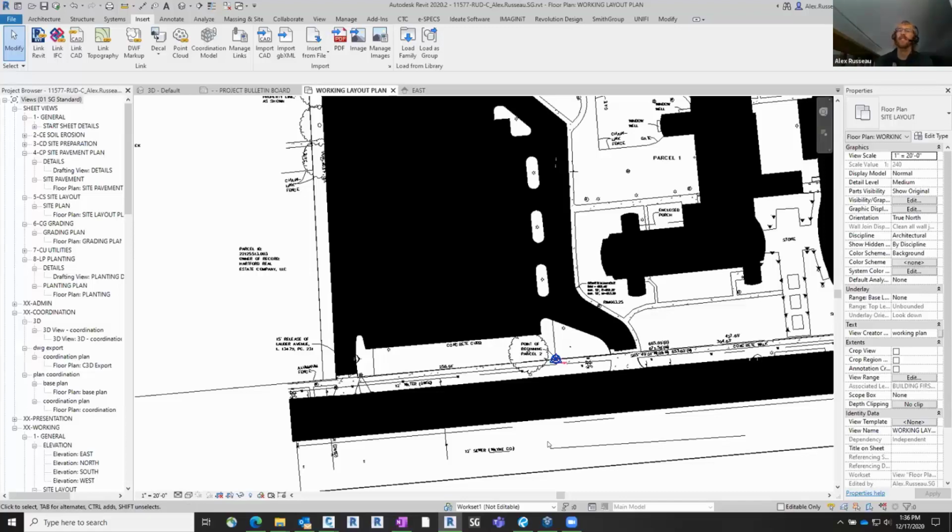Yeah, it's the coordinate translation between a shared coordinate system and the project coordinate system. It does need to make a translation in Revit versus Civil 3D. It's just always real world coordinates. When I link in this file here, it was dumb to start. I brought it in origin to origin. It had no data in it. So that's where we need to move it initially. After you set up the shared coordinates, that's when you never want to move the file. It should be reliant upon the shared coordinates then.